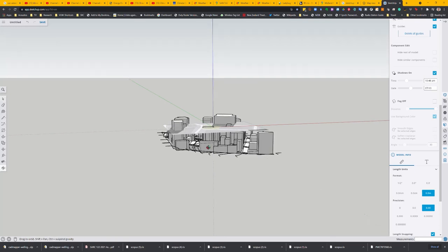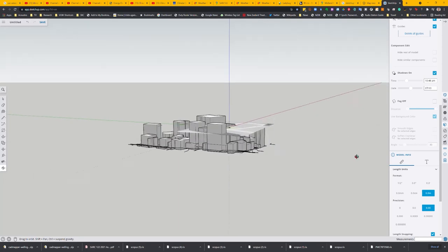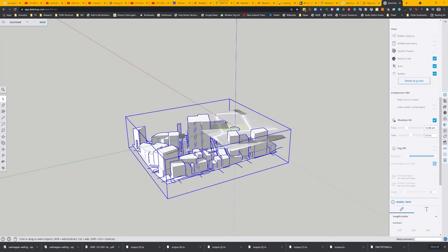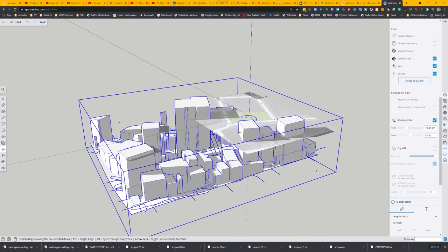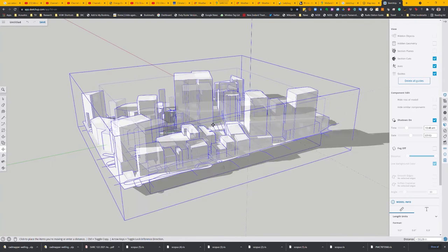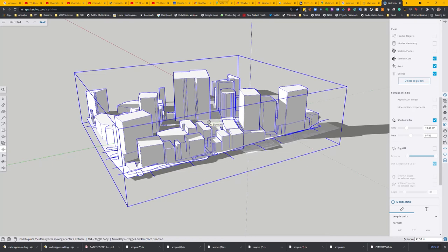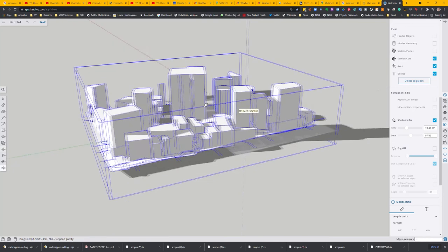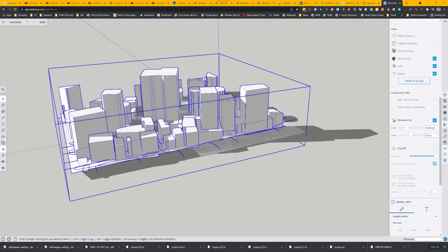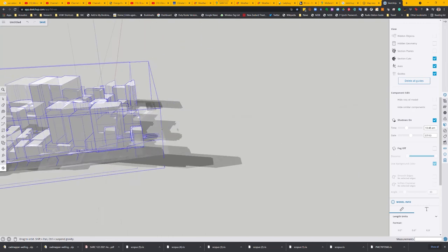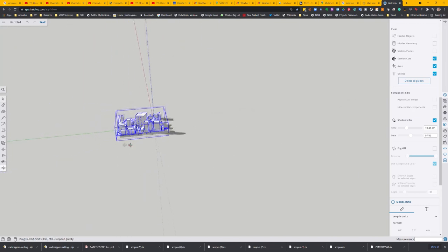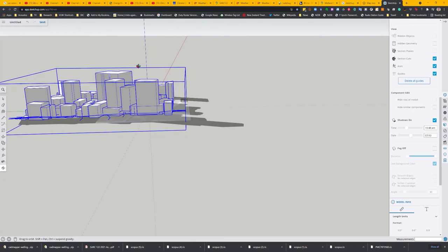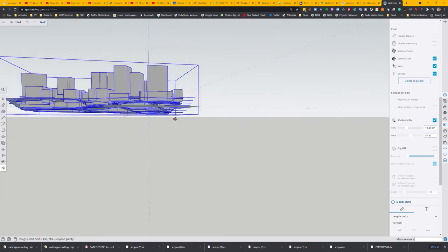Now I've not quite got the building at the right level. Let's choose this building. I'm going to press M again, pick that endpoint and try to move it vertically on the blue axis until it's at the point of the surface where I've got the geometry vertically aligned with the map that I've already downloaded, just to make sure that I am in the right place.